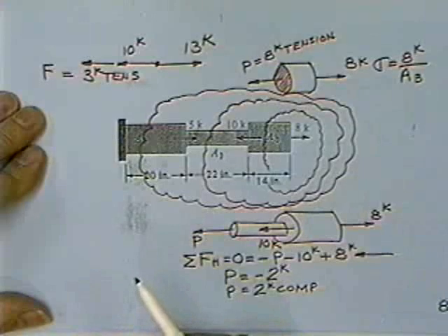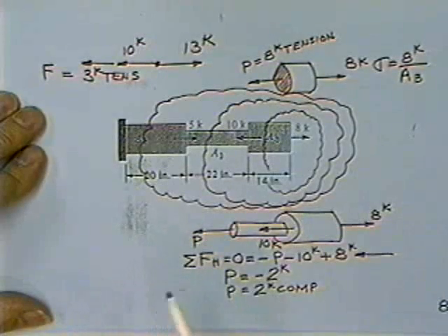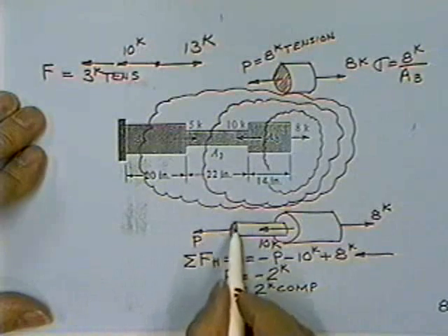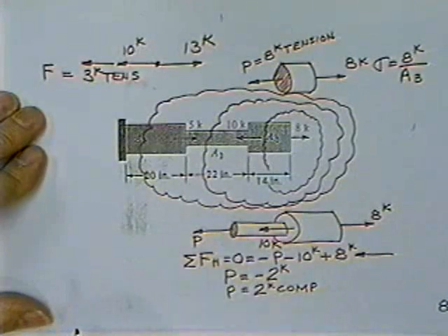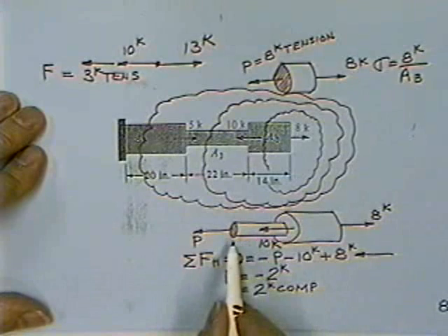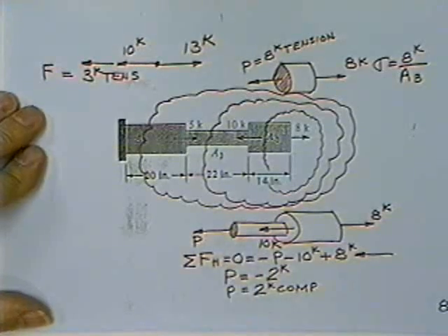As soon as I found what the value was, I'd stick it in there, that'd be the stress. Same way on all the rest of them. You'd simply take the force applied across the cross-section, divided by the area of that cross-section, and that's the stress in there.